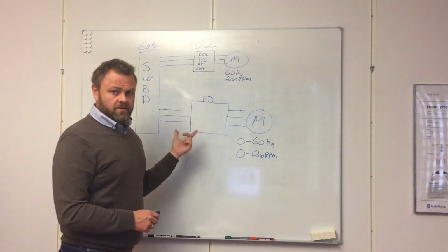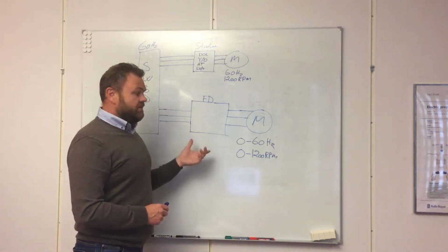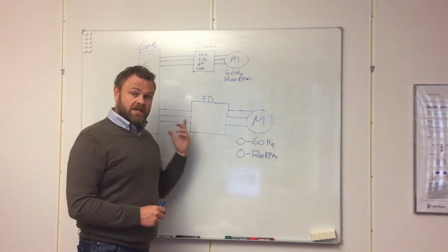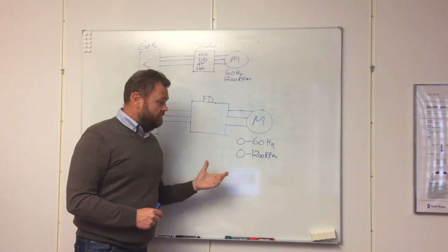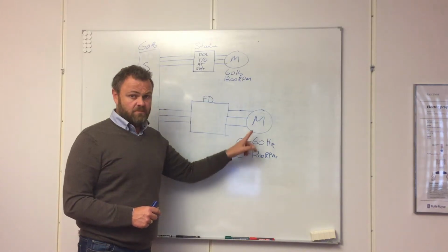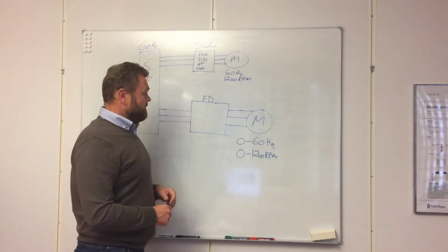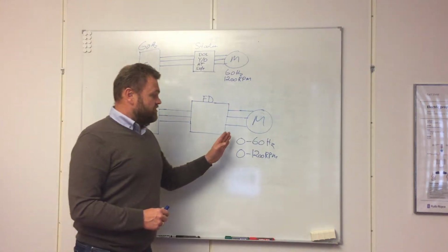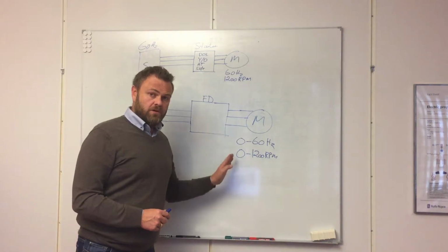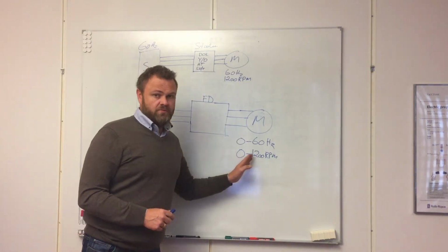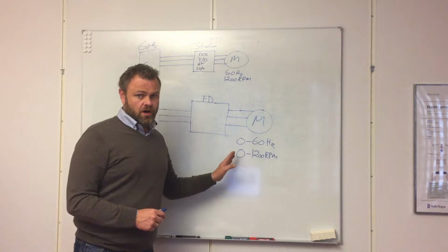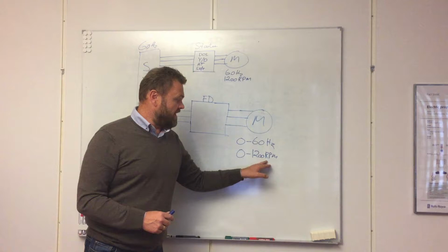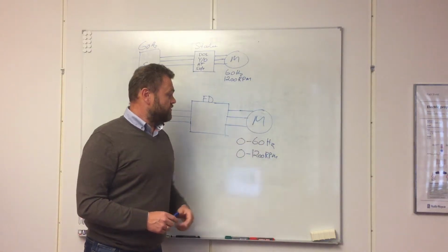The frequency drive, however, will give you a very smooth start and will give you a smooth ramping up of the RPM of the motor. So the frequency drive will give you a smooth start and full control of the RPM regulation throughout the complete area of RPM you have for this motor.